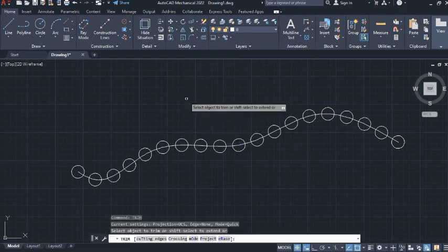We can easily come here. Once you see this X, you take your mouse to the line you want to trim, and before clicking, AutoCAD will show you this X on top of that cursor, and it says that okay, this is the object you want to trim, and you left click to confirm, just like that.